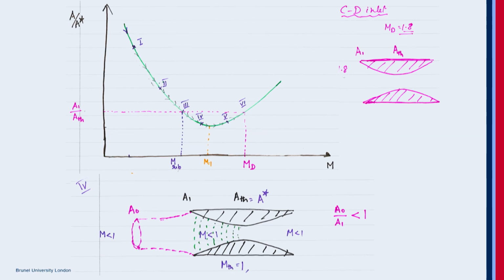So you can see that the pressure, the green lines here, the pressure wave starts to build up. The pressure wave starts to build up as we try to accelerate it. So you can see that still it is subsonic in the convergent part. It is choked at the throat. The pressure waves are building up here. Still it hasn't reached M equal to 1.